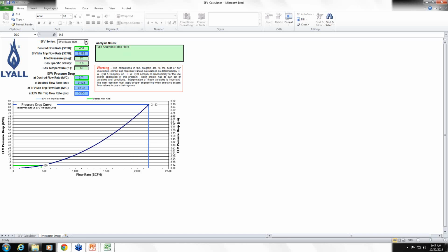And then you do your own calculations on your service line length protected and all the different configurations you have on your service line with the different fittings, and you do those calculations yourself. And you just want to know what's the loss due to the excess flow valve with the conditions and flow that I'm